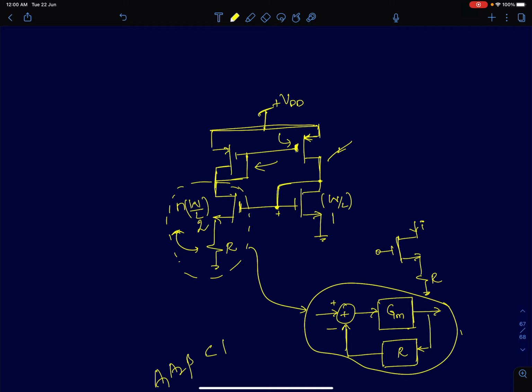There are circuits, for example some bandgap references or some niche ones, probably in analog charge pump PLLs, where we have some charge pump architectures which use a combination of positive and negative feedback. But even in all those circuits, negative feedback will either dominate, or if positive feedback dominates, we will ensure that the loop gain is always less than 1. That condition has to be ensured. I gave you some simple reasons why it should be ensured.